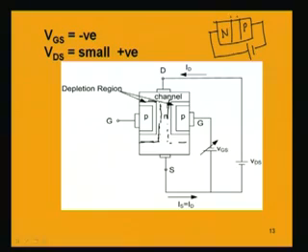It is like the threshold voltage in the depletion type MOSFET. In the depletion type MOSFETs also we have seen that there is a threshold voltage below which the gate to source potential should not go, because then the current will be 0. Similarly here, this pinch off voltage is that voltage between the gate to source, it is negative, mind it, at which the drain current becomes 0.